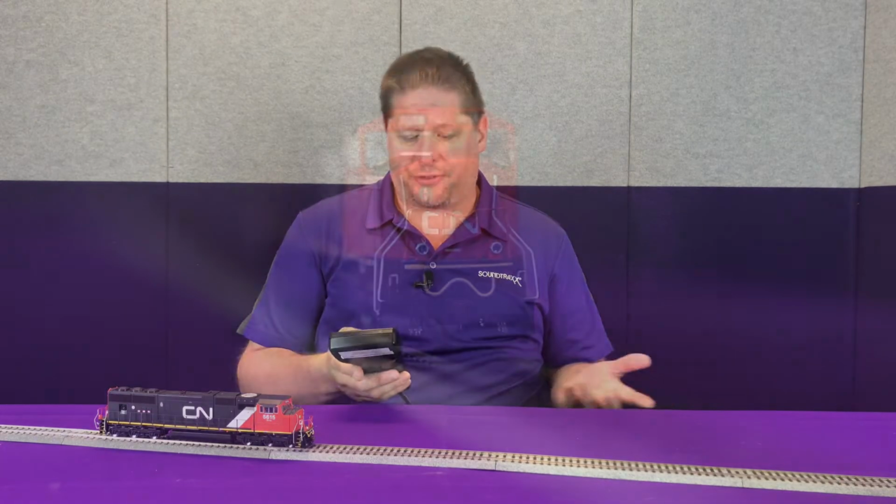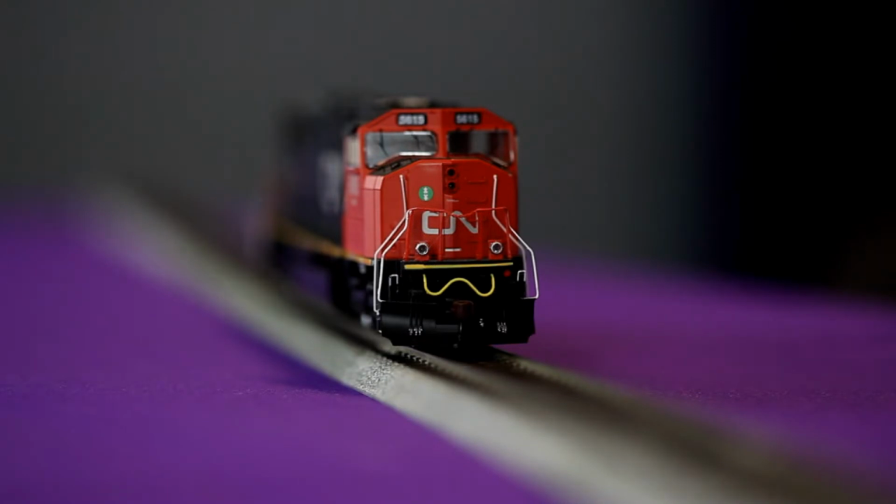So out of the package, function 0, as we mentioned, in forward direction, turns on our headlight. Now function 24 will turn on our FX3, and in this case I have it set to one of my ditch lights. Now the FX4 is controlled by function 25, and so now I have that set up to my other ditch light. So now you can see the headlight and both ditch lights are on, but I had to enable 3 different buttons to get that to work.